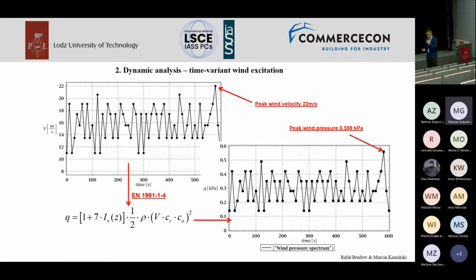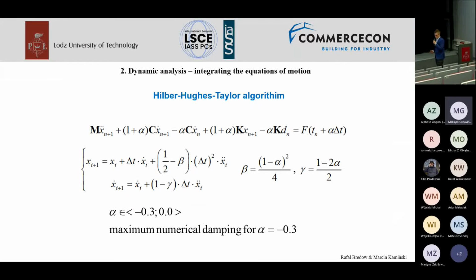As for the dynamic analysis, this structure has been subjected to the dynamic wind excitation in a 10 minutes time interval, and this wind velocity spectrum underwent further calculations following the Eurocode 1 statements, so that the dynamic wind pressure in the 10 minutes time interval has been found, including the orientation and the orography of the terrain of this real structure.